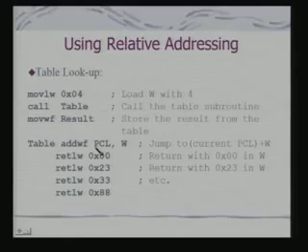If you see here, the current content of W will be added to PCL, and you will jump to the current PCL plus W. So, the moment this offset is added, the current location is PCL plus W, and this has been done through an arithmetic operation. We have not executed any branch instruction at all. This is very, very interesting. We have not executed any goto or conditional branch, we have just done an addition operation.